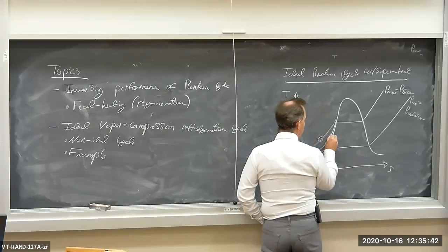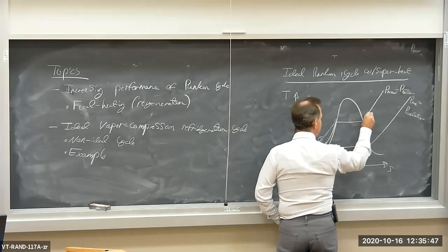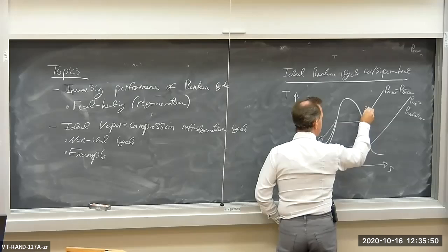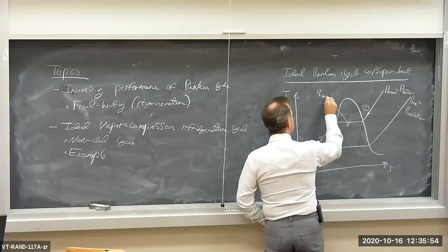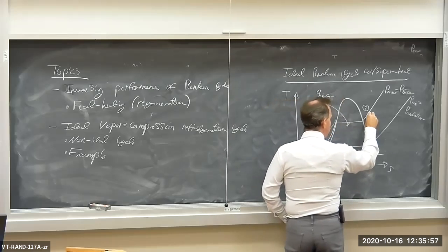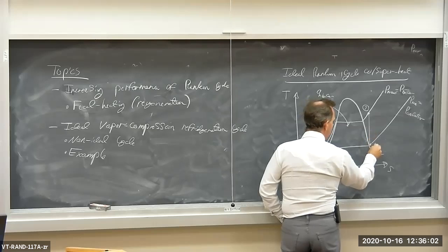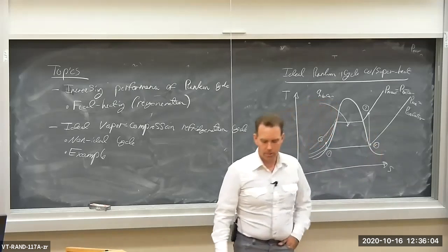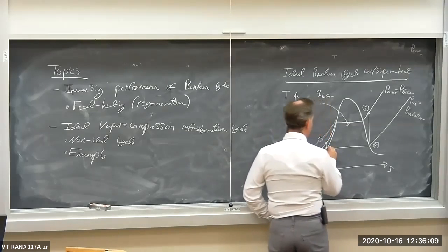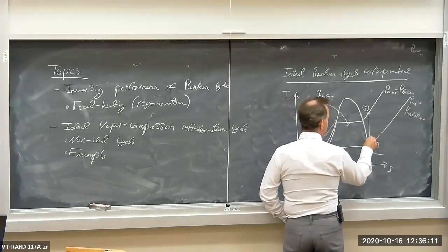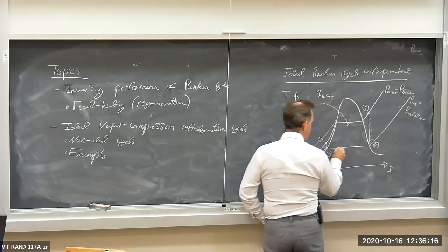And then in the ideal cycle, we have constant pressure heat addition in the boiler up to some sort of superheated state at state 3. So this is our Q boiler. And then presumably we have an isentropic, because it's reversible and adiabatic, ideal expansion in the turbine. No heat transfer in the pump, no heat transfer in the turbine. And then we have heat rejection in the condenser.